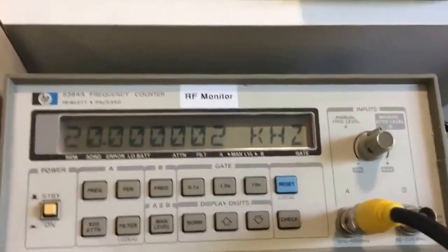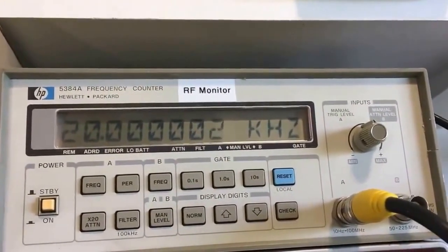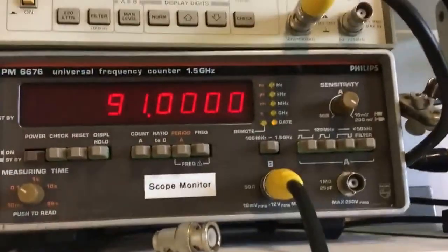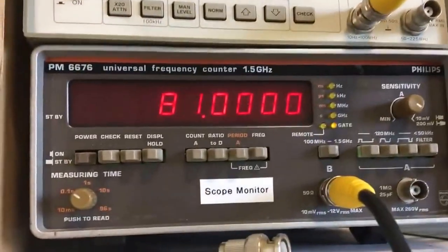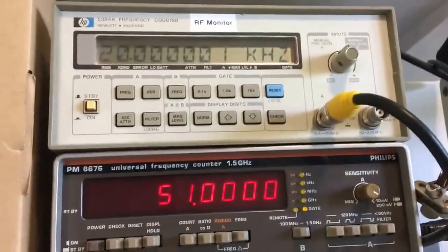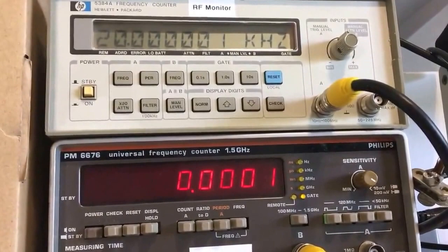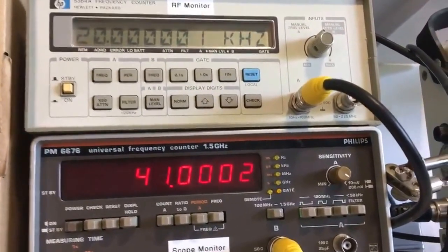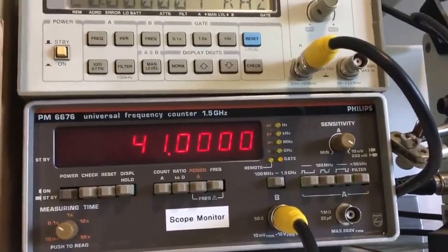So that's what is at test point 11, and it should be 20 kilohertz. And you see how close that is. That's really, really good. That's the output of the generator right now. So I'm stepping down. If I zoom out a little bit, there you go. You can see that 20 kilohertz. Ignore that zeros. That's because it goes below the limit of that input. That input's got a 100 megahertz input, and below that, so it's dropping off.